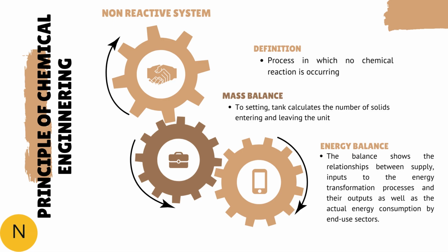It also considers the input, output, and distribution of streams in a process. The mass balance equation simply states that the total mass in any system is always conserved, which is to show all CO2 and H2 go to the top of the product. Other than that, acetic acid and water condense to form a liquid mixture which is going to the bottom product.